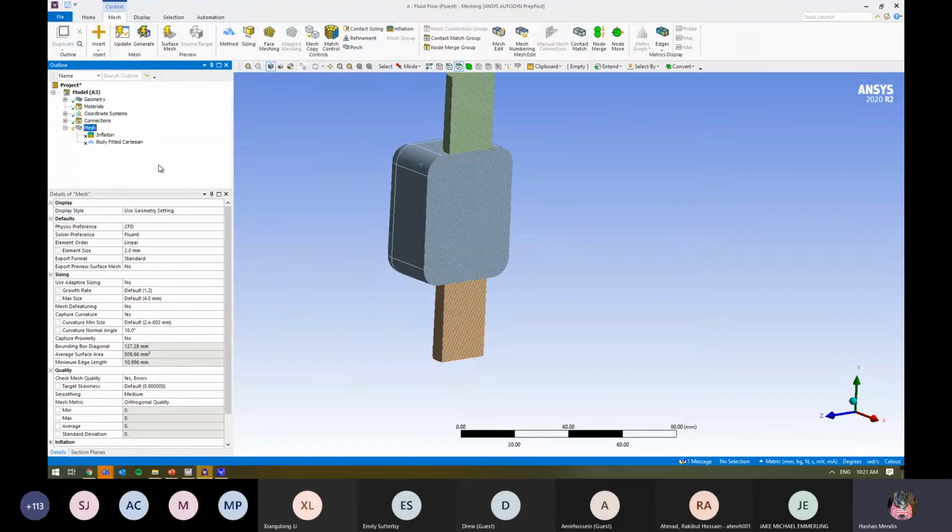Can we define mesh types locally? Like switching hex to poly in one element. So Cindy, yes, we can. No, we can't quite do that at the moment. We can't just switch from a hex to poly in one element. Either we're using tet elements or we're using poly elements, and then the formulations for the hex core and poly hex core will determine where it splits from one to the other. We can't use hex core or poly hex core in Ansys meshing. We'll use that in Fluent meshing, which I've got an example for a little bit later on.